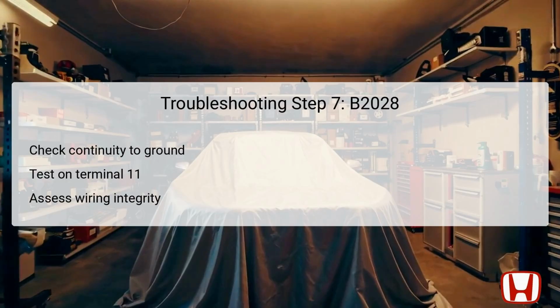without unnecessary interruption. Should the continuity test reveal a connection to ground, this suggests a short circuit in the wire, necessitating urgent repairs. Conversely, failure to find continuity furthers the investigation into potential faults within the control unit or its connections. This step underscores the importance of electrical circuit integrity in vehicle diagnostics, as a single faulty wire can impede essential functionalities. Through this troubleshooting measure, technicians gain valuable insights into the condition of the sliding door system's wiring.